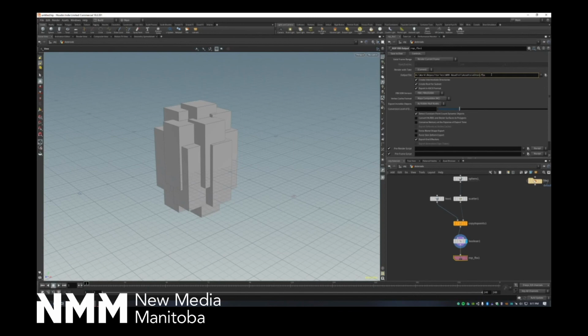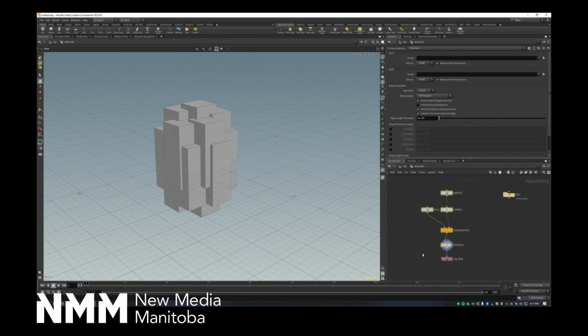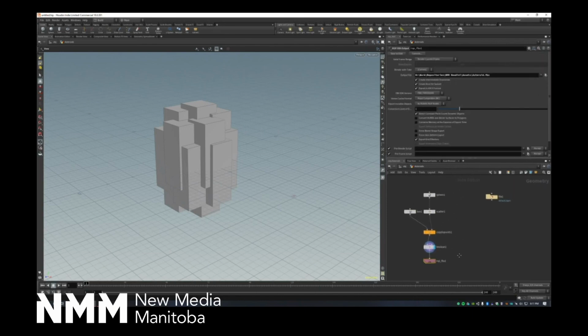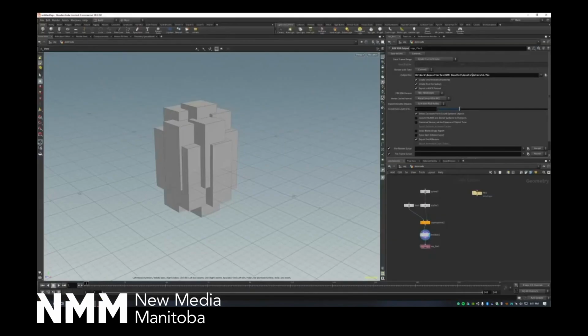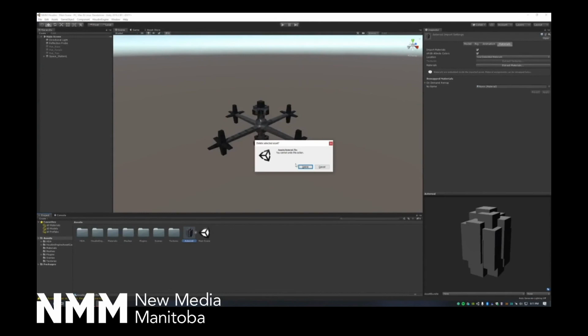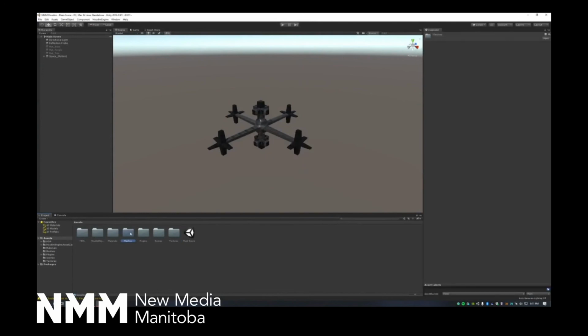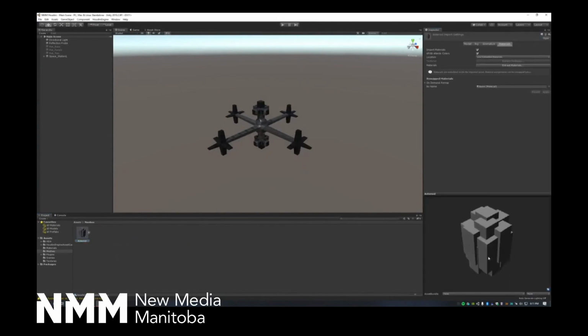We're going to call it asteroid FBX. So we'll save to disk up here. And then that'll just save everything that's being plugged into this node to an FBX, as you'd expect. Go back to our Unity project. I saved it to the wrong folder. We'll just fix that real quick. Assets, meshes, asteroid. Save it again. Let's head back and delete this old one. And in our meshes folder, we've got our asteroid.